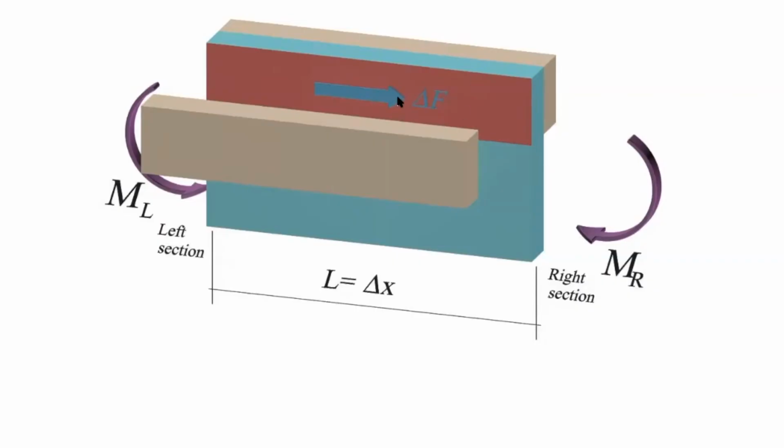Now, because I have determined shear flow, which is the balancing force in the unit length, it means that I'm going to consider the area for 1 unit length of the beam. So L, or delta X, is going to be 1 inch. But how much would be area in that case? The area of this rectangle for the unit length would be 1 multiplied by this dimension. So this is going to be the thickness that we are going to consider.